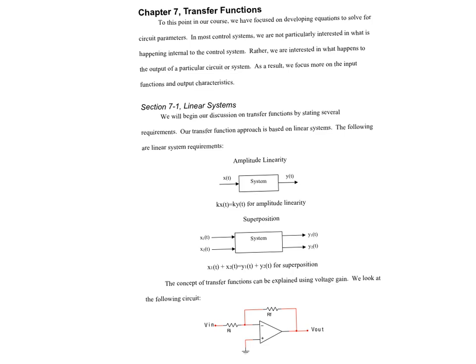That's what we're talking about with transfer functions: we're going to take our circuit analysis and break it down into smaller parts and then tack them onto the end. For those of you who are doing the senior project sequence currently, you're probably doing that already. You just don't realize it. You build one part of your circuit, get that working, and then you work on another part of your circuit, get that working, and then maybe you work on a third part, or however many parts you have, and then you interconnect them to see how the whole system responds, right?